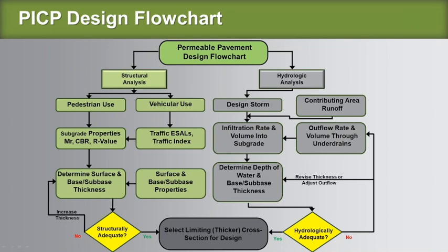And so we do a few different things to be able to get more water into the ground with those kind of soils. We look at the traffic, how many ESALs, the equivalent single axle loads that we have using the pavement surface. Talk a little bit about that more as we move through here. And then ultimately, we determine how much strength do we need to accommodate that design traffic over time, and we design the pavements for that.